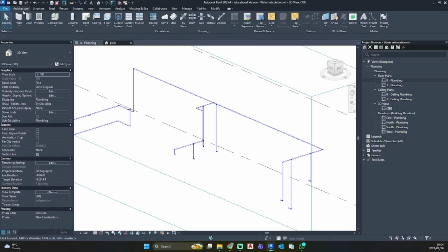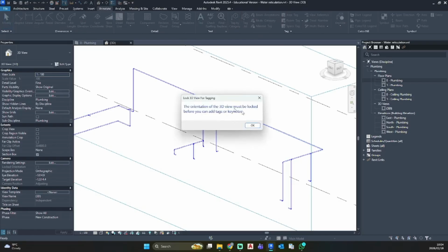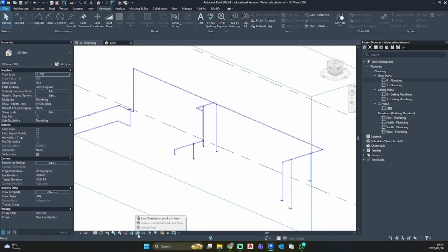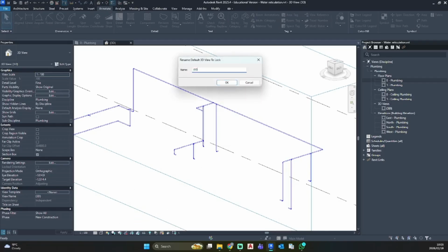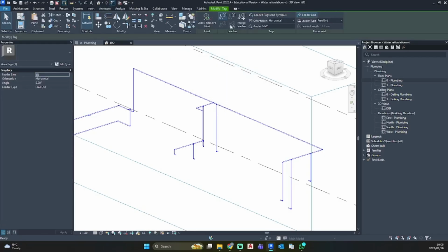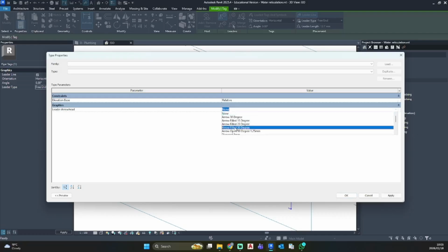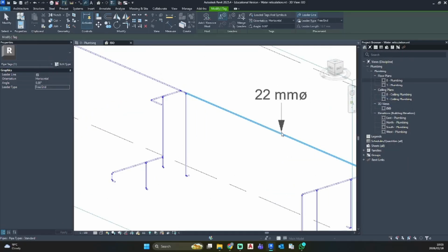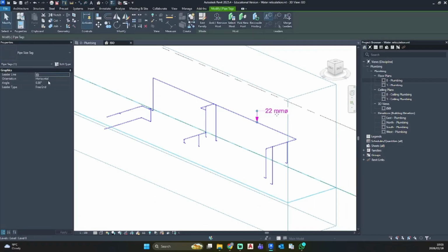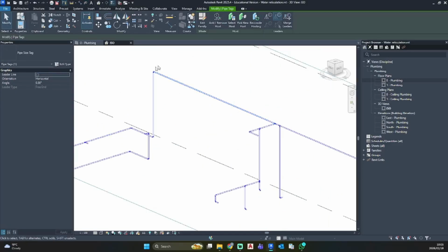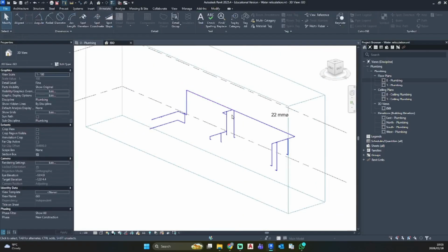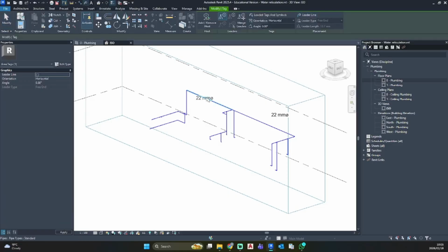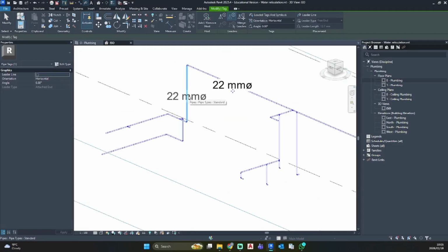So later on we will be going to annotate, tag, we need to lock it, so I'm just going to do that now. ISO, tag, and now it's going to use attached ends, go free end, add an arrow fill, and now we can do this. And if we don't want a leader head, we can go and tag, switch off leader head, and we can do this.